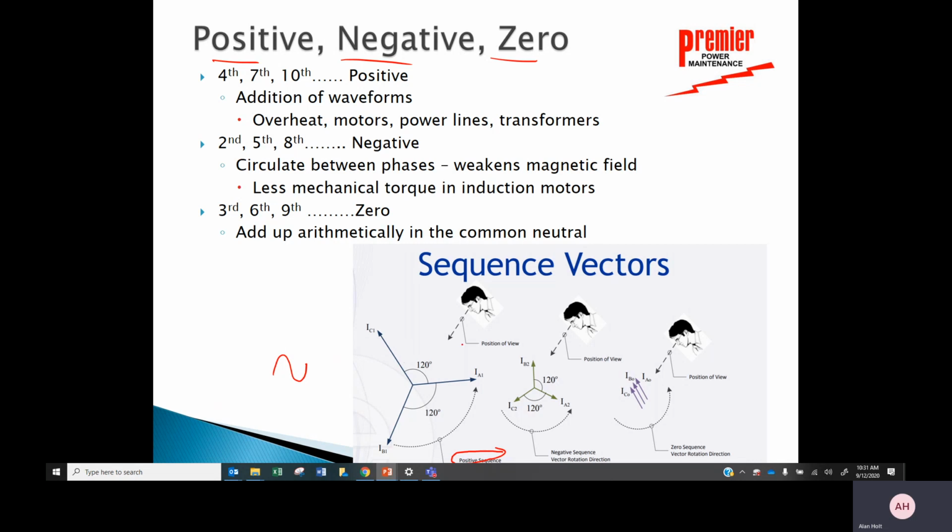So in the positive world, as I'm looking, I can see A phase come by, and then B phase rotates by, and C phase rotates by. And that's just the little world I've got. And that's a balanced three-phase system. Okay. And then I have this area where I call negative sequence. Anytime I have an unbalance, no ground fault, but just an unbalance, I have these same currents, but now they are rotating A, C, B, not A, B, C.